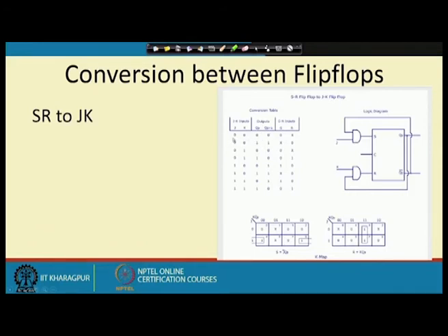From the JK flip flop we know if it is 0 0 0, Qp plus 1 is also 0. If it is 0 0 1, it maintains the previous value, so Qp plus 1 equal to 1, that is equal to Qp. If it is 0 1 0, then irrespective of the value of Qp, the output is 0. So, Qp plus 1 is 0. So, 1 0 0.